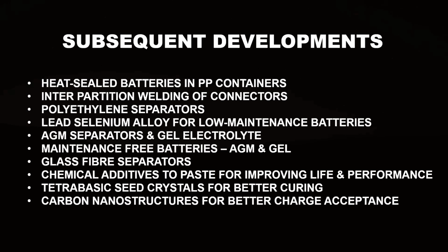There was another maintenance-free battery that used a gel and mixed sulfuric acid with certain silica and other additives. The gel electrolyte batteries are also maintenance-free. Thus, we have maintenance-free batteries of both the AGM and gel types. Subsequently, glass fiber separators were also introduced. The glass fiber separators were introduced for use in conjunction with polyethylene separators for low maintenance pasted plate batteries.